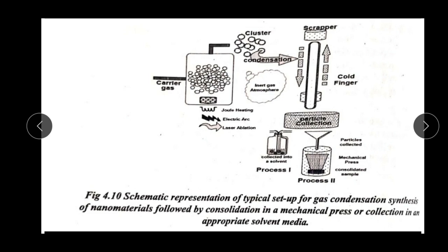Originally a rotating cylindrical device cooled with liquid nitrogen was employed for the particle collection. The nanoparticles in the size range from 2 to 20 nanometers are extracted from the gas flow by the thermophoretic process and deposited loosely on the surface of the collection device as a powder of low density and no agglomeration.